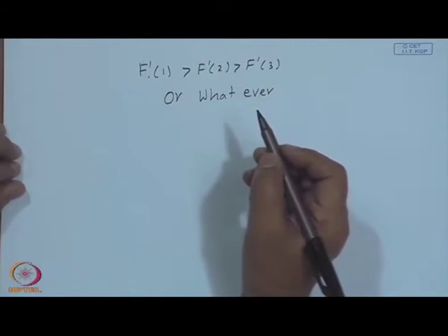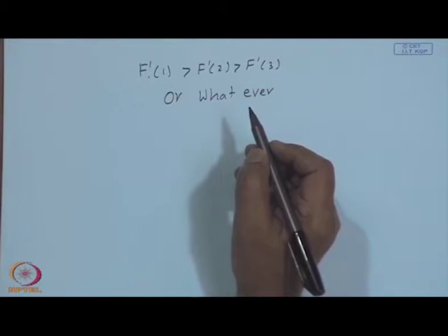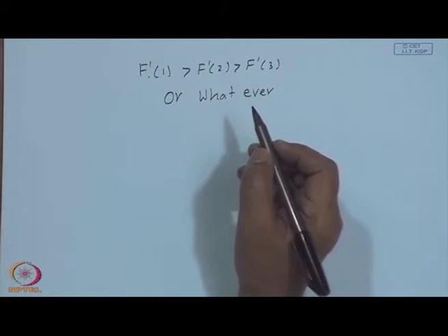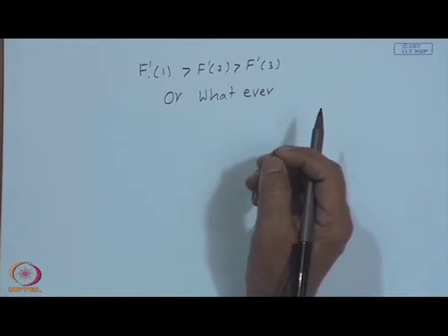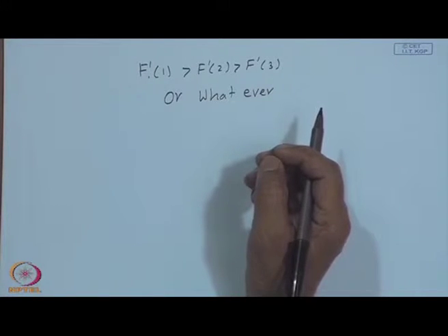Or else one can take a particular material, thickness delta, W and U_L, and compute these numbers for the fin efficiency and the collector efficiency factor, and find out which one is better.